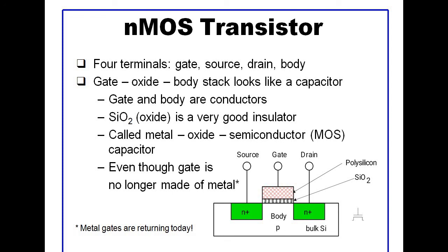These structures are manufactured using a series of chemical processing steps like oxidation of silicon, diffusion of impurities into the silicon to give it certain conduction characteristics, then deposition, and lastly etching of the aluminum or other metals to provide interconnection. This is carried out on a single crystal of silicon, a thin flat circular wafer around 15 to 30 centimeters in diameter.